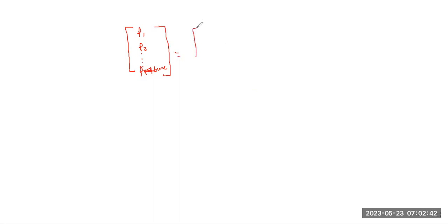So we can write this in terms of P1, P2 up to Pn buses, up to the last bus, Pn. Then this Bx would be the matrix part of the bus values. Suppose you are having different buses, where Bx can be expressed as b11, b12. If you have two buses, then it would be b11, b12, b21, and b22, right?